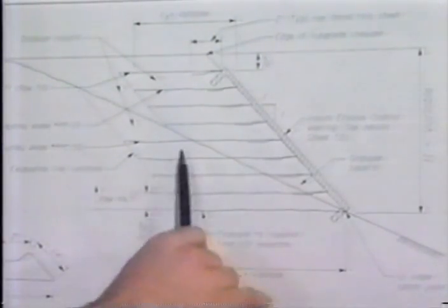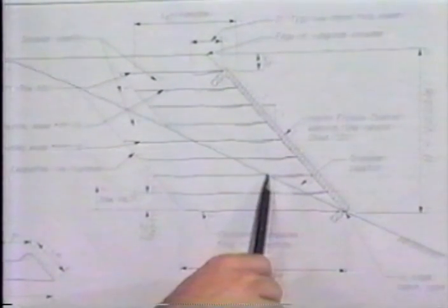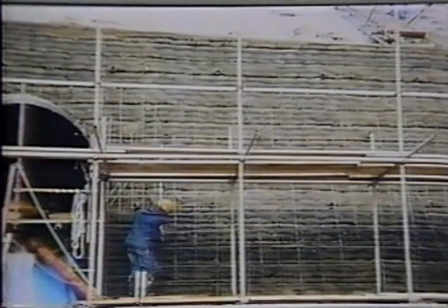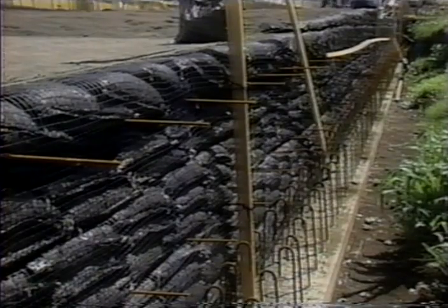The design analysis of steep slopes is, of course, critical. If the reinforcement fails, the slope will fail. The same applies to mechanically stabilized earth walls. Retaining walls in transportation engineering are required where a slope is uneconomic or technically unfeasible. Mechanically stabilized earth walls, MSE walls, contain some type of reinforcing elements in the soil to help resist lateral earth pressures. For nearly 20 years, geosynthetics have been used as a viable and economical reinforcing element in vertical or near-vertical walls.